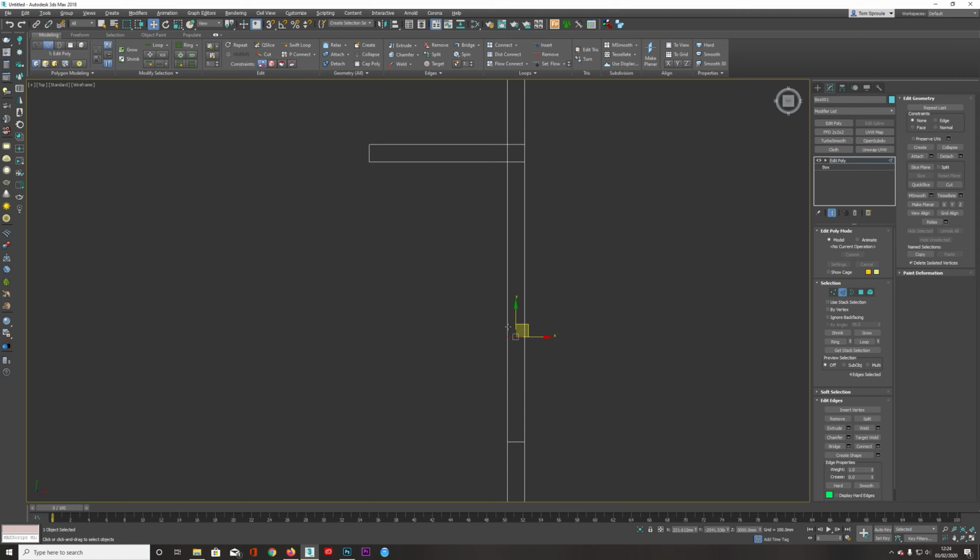And so now, I'll show you another thing I have on your snaps here. If I press S to turn on snaps, if you right click on this, go into options, and I always have enable axis constraints. I mean, I don't always. Sometimes I come in and turn this off, but by default I turn this on. And then by default my snaps, I always turn those on to vertex. These I just left at default for now. Sometimes I change this. This is for the angle, and this is percent. But for now I'm just turning on this and going on snaps vertex.